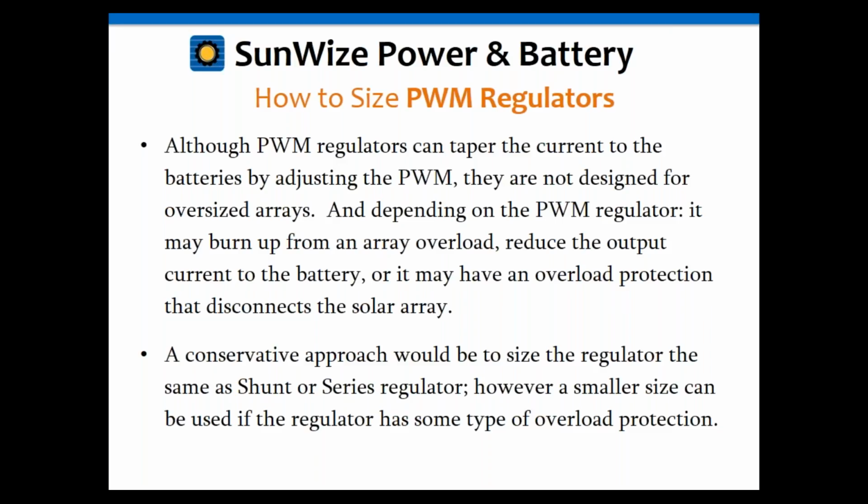So in all of these situations, it's very important to size your regulator correctly so that you do have reliability for your system. You don't want to cut things close and accidentally have it melt down. The other thing is that transistors don't like to run hot, so if you've sized your system in a gray zone, running it at its maximum, then you'll find that your regulator may not last quite as long.